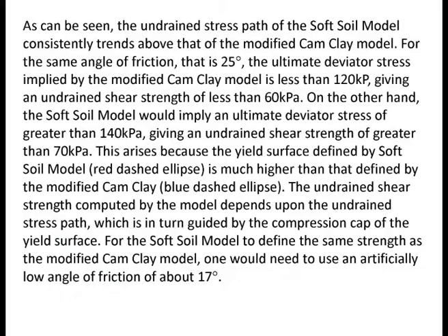So basically, the Plaxis, for the same angle of friction, will give you something higher. And so in order to lower it down, you have to use possibly a lower angle of friction. Instead of 25 degrees, you may use 17 or 18 degrees to compensate for that, to be in line with the Cam-clay model.